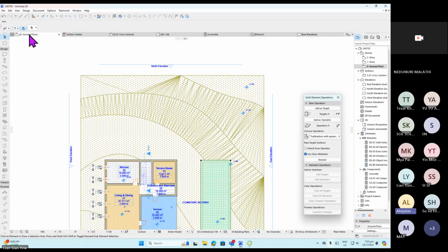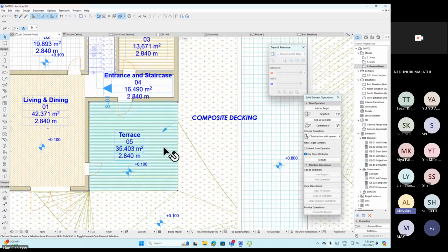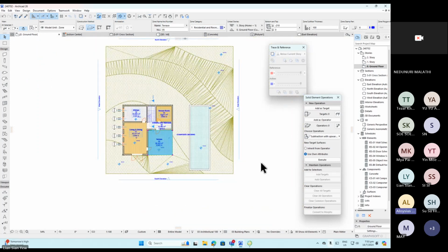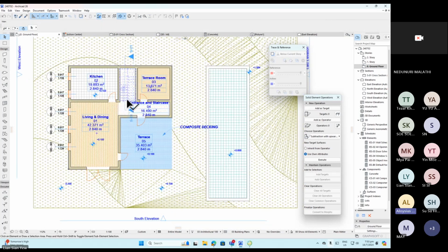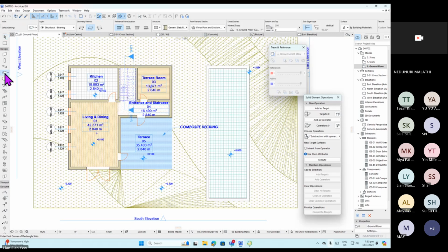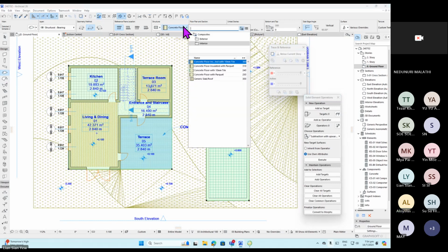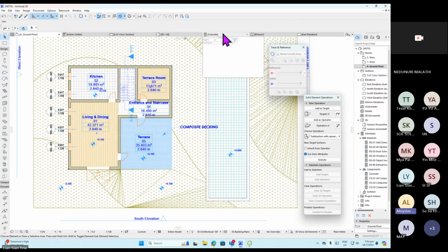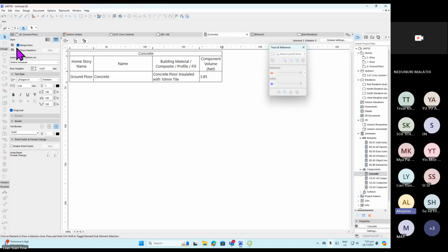Okay, so just make sure that you have some things that are concrete. Because I realized that I didn't change my slab earlier on. Oh, one shortcut is you can select slab and you just Control A and you will choose all of the project file, and then now you can apply them to be concrete. So I can merge them or I can unmerge them.